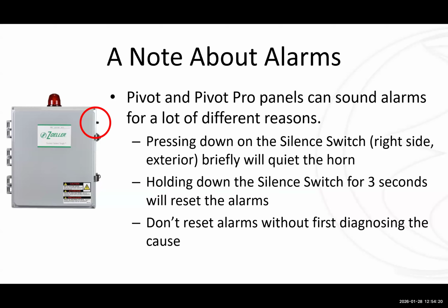And it's good to know because if you're trying to fix something, right? Is it alarming because the floats came up out of order? Is it alarming because you actually had a high water alarm? Is it alarming because you have a seal fail going off? It's important to identify what alarm it's telling you before you reset it.